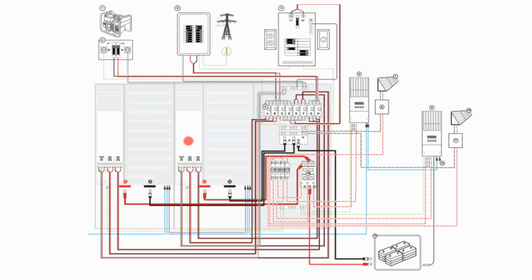Your generator and your inverters generally have to be the same size. Well, it depends. If your generator is flowing through your inverter, then your inverter needs to be the same size as the generator. Otherwise, if that generator power tries to land on these bus bar terminals, they may overheat and burn up the terminals. If your generator is undersized compared to the output of the inverter capacity, you should be okay, although an undersized inverter has to run longer.